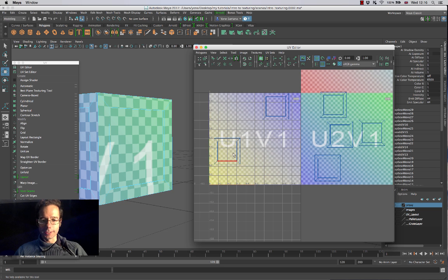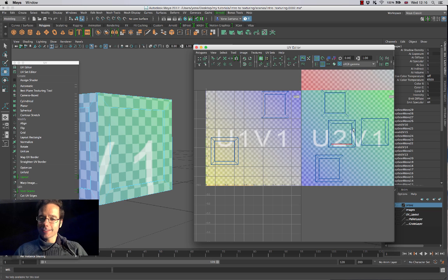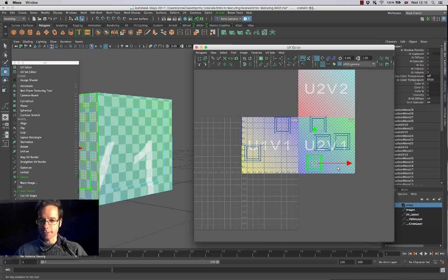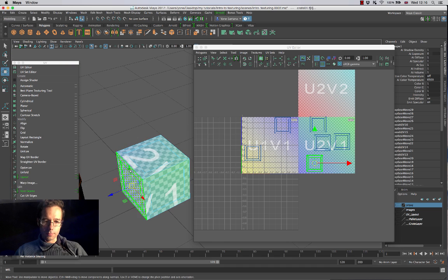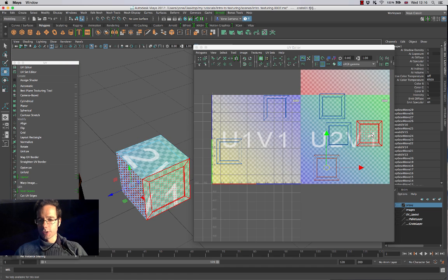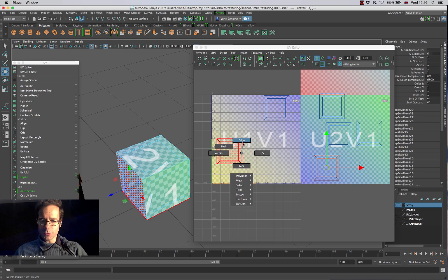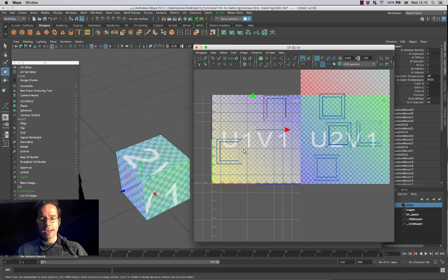Very much just by going in, fixing it one edge at a time because it was jumping all over the screen. And now I end up with, again, some major shells inside of my UV template over here. And what I want to do is piece them back together so that they form one single shell. So I'm going to glue them together. I don't have to be very specific at this stage in terms of how they look, but I'm going to come into edge mode over here, select an edge, and do a move and sew one more time to connect these two pieces together.